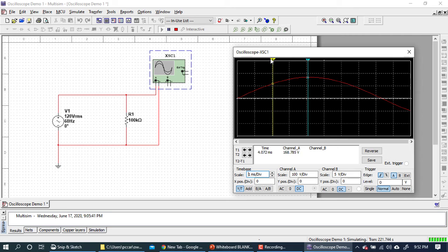We'd have to find out how much time is in 90 degrees, which will be, what, a fourth of the period. Remember, the period was the time that it took the whole cycle to occur, which we said was, what, 16.666? 16.66667 milliseconds divided by 4 equals, I got 4.1666667.